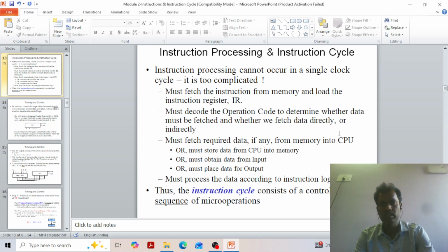And instruction processing and pipelining. Instruction cycles mean how the instructions are executed in a sequence of micro operations. It has 3 parts: fetching, decoding and execution. So the pipeline stages can be organized: fetching the instruction from the memory, calculating the address for the data, and fetching the data before the execution part. So it can also be separated into one separate stage.